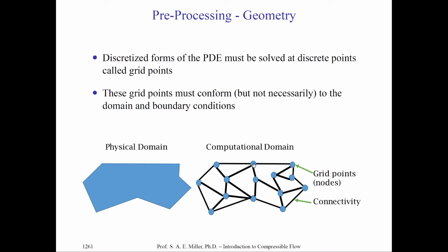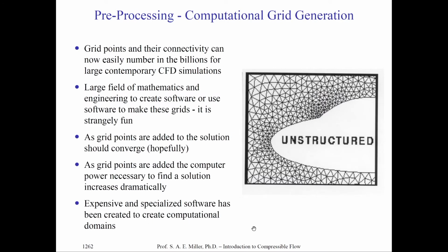For example, we will know the solution at every particular grid point and how that's connected to other grid points with the CFD solver. This is what we call an unstructured grid, meaning that the grid ordering is not intuitive. It's not ordered by an implicit method. It's explicitly stated by the solver. Grid generation, indeed, is the most time-consuming part of CFD, at least for people. The most time-consuming part of CFD for computers is in the solver stage.